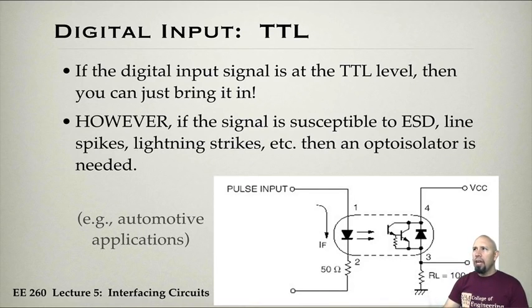First of all, we have TTL interfacing. And again, we may be in an environment that is very noisy. The theory says that we have a digital signal at TTL level. However, the real world is still basically analog, which means even though we think that's 5 volts, it may be fluctuating. And it may fluctuate to the extent that it would fry our Arduino. In other words, you can get voltage spikes that would cause the Arduino to fry. Not a good situation.